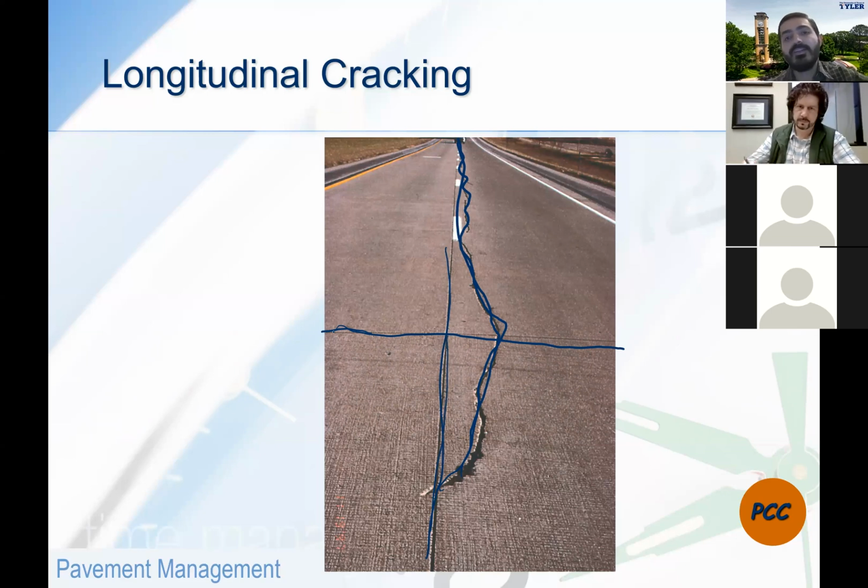Sometimes again, the contractor just wanted to come anyways. There is a crack. They just want to do whatever they're supposed to do, although it's late. But they just did it to satisfy the job. But really, it's a late saw cut job, and that's why the crack will initiate.